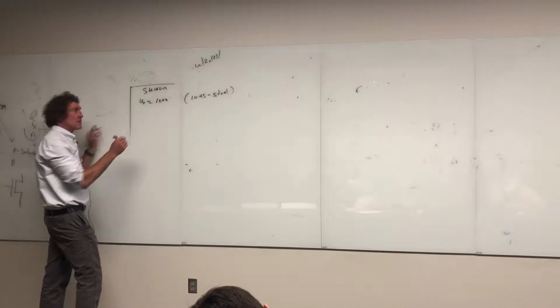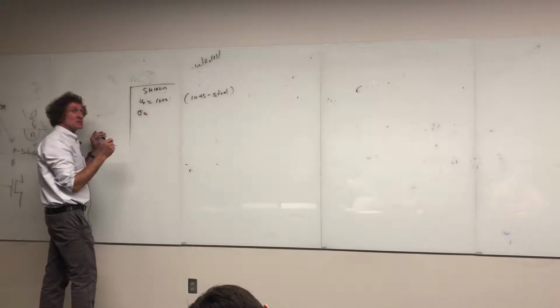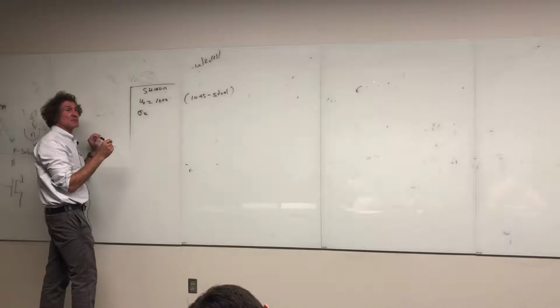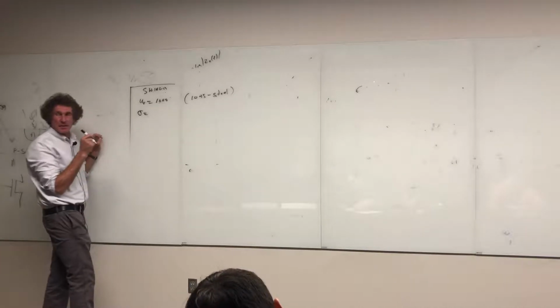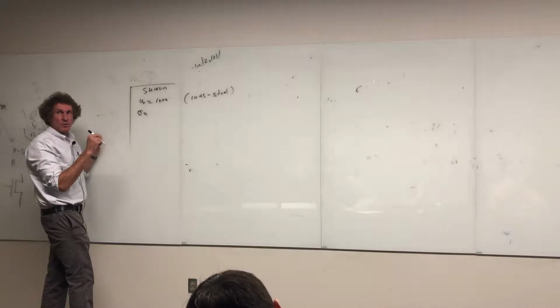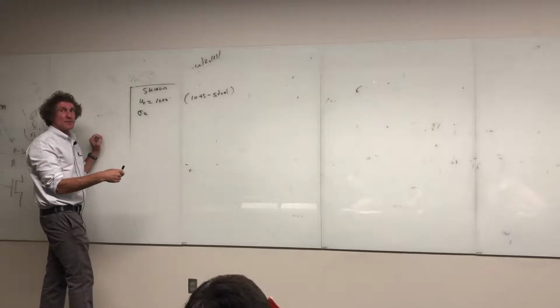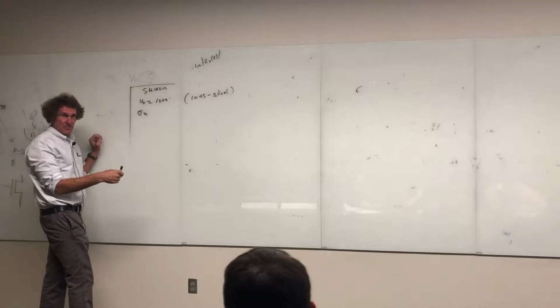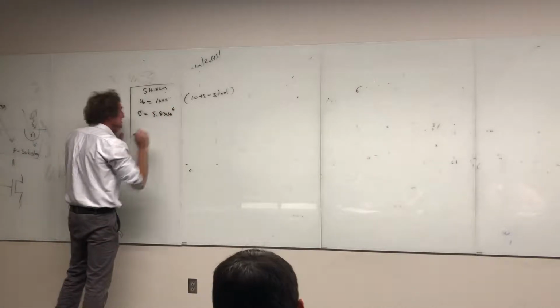Now that's mu relative. The other thing is the actual sigma for this typically is given as sigma of copper times a multiplier. Well, the multiplier is 0.1 if you look at that table. Did anybody look at that table? All right, the multiplier is 0.1. Well, the conductivity of copper is 5.8 times 10 to the 7th. Times 0.1 is 5.8 times 10 to the 6th. Do you all follow me on this? So this is going to be 5.8 times 10 to the 6th.